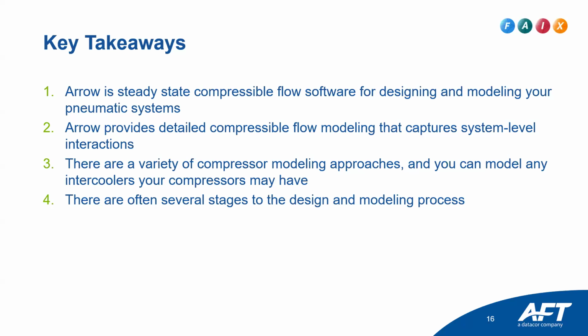Three, there are a variety of compressor modeling approaches, and you can model any intercoolers your compressors may have. For the intercoolers, you can model the cooling loop as well, whether the fluid is a gas or, say, a liquid, using heat exchanger linking. Four, there are often several stages to the design and modeling process. Again, we have a scenario manager to make each iteration easier to deal with. Changes to one scenario will propagate to the children. So if you decide that you actually needed a different pressure for that tank at the end, for example, you could change that and it would propagate into all the rest.